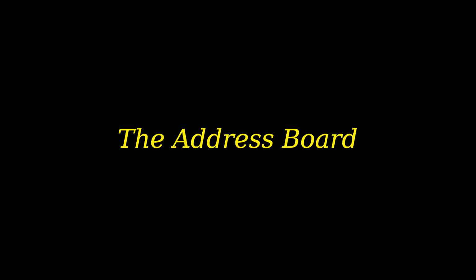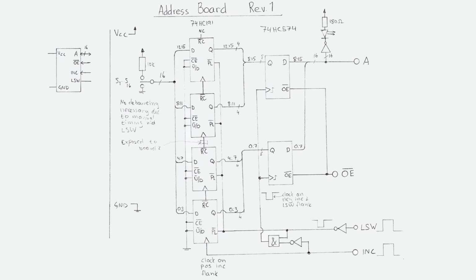Now that we know what the INC and LSW signals mean, we can have a look at the address board. There are 3 major parts: the set of switches, a cascade of 4-bit adders, and 2 8-bit registers. Much like on the data board, there is a set of LEDs outside the register, which indicate the status of the bus irrespective of who is actually driving the bus. When the LSW pulse comes, the PL inputs on all counters go low, which causes the adders to load the values set on the switches.